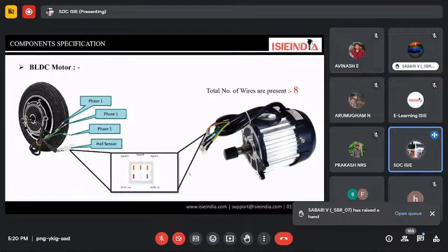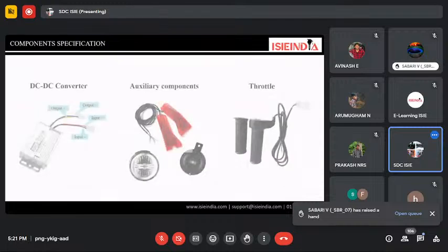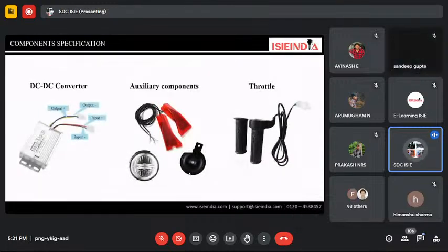In each BLDC motor, there are 3 sensors, and these 3 sensors sense and give an analog signal, and those signals are the signal A, signal B, and signal C wire. To run that sensor, we need a very small amount of power, like 5 volt. So we deliver a red terminal wire along with a black terminal wire, as positive and negative, to each of the Hall effect sensors. So we can see all of the basic components.